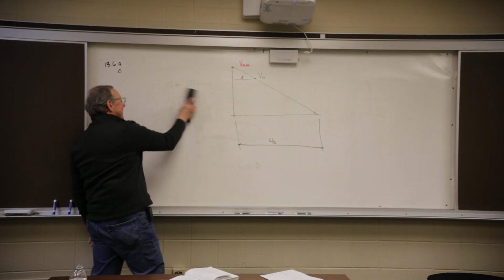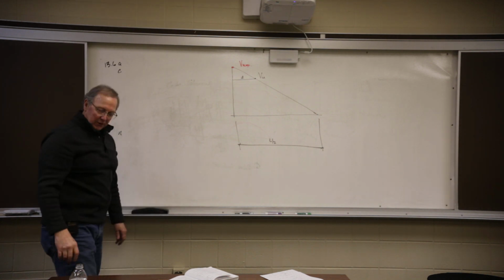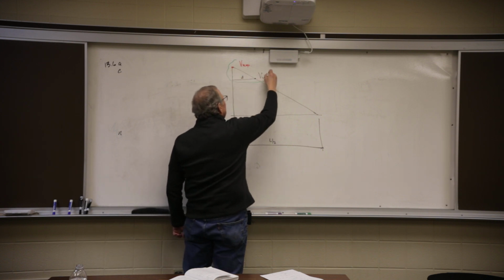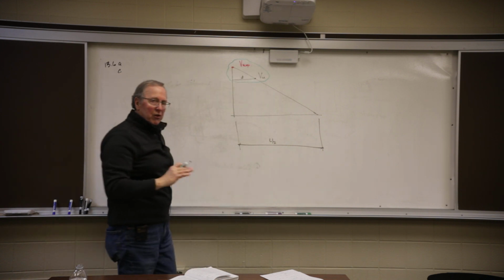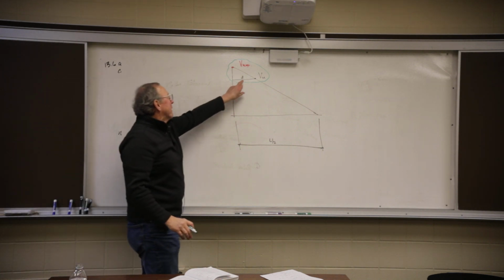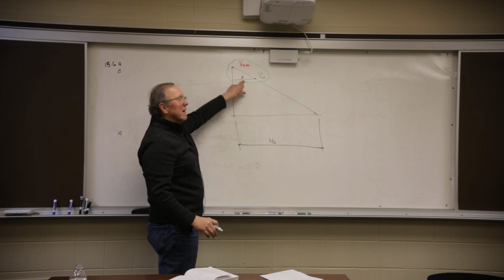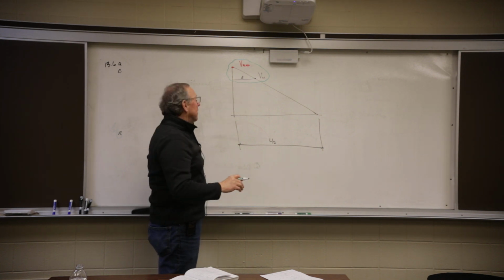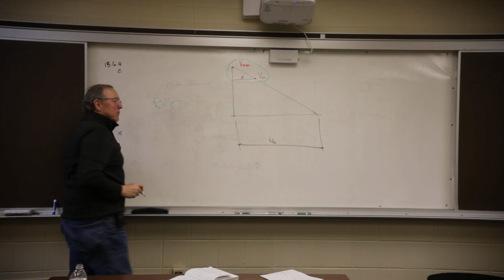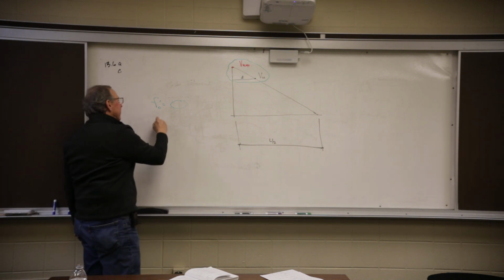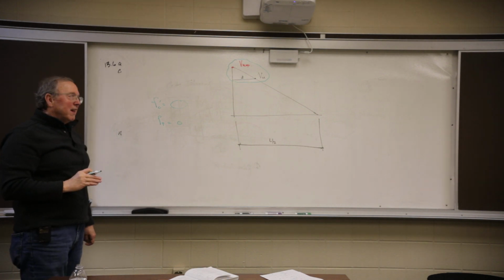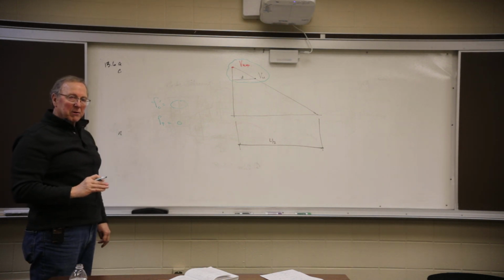Okay, so now I've got the load requirements. So these top two are numbers that are generated based on your shear diagram after you factor the loads. Now, this is the requirement for shear. What can the concrete contribute? Well, we indicated concrete has a compressive strength in PSI. We also indicated that the tensile strength of concrete is 0, but the beam has shear strength capabilities.